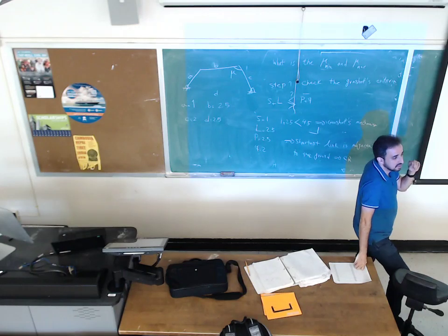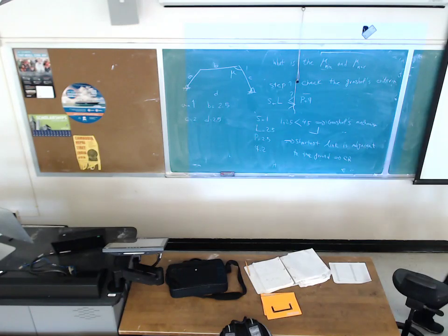Yes? Can you quickly go over what you said about the coupler? What I'm saying is that in this equation we have B, C, A, and D. B representing the coupler. No matter how I label the mechanism, B should be coupler, C should be output, A is input, and D is ground.